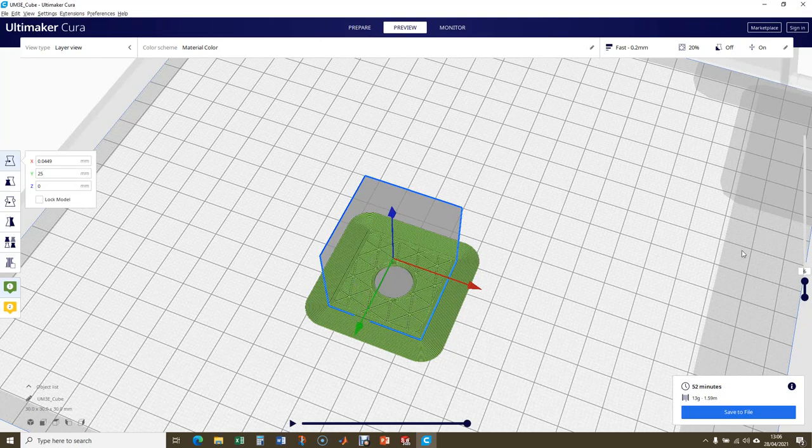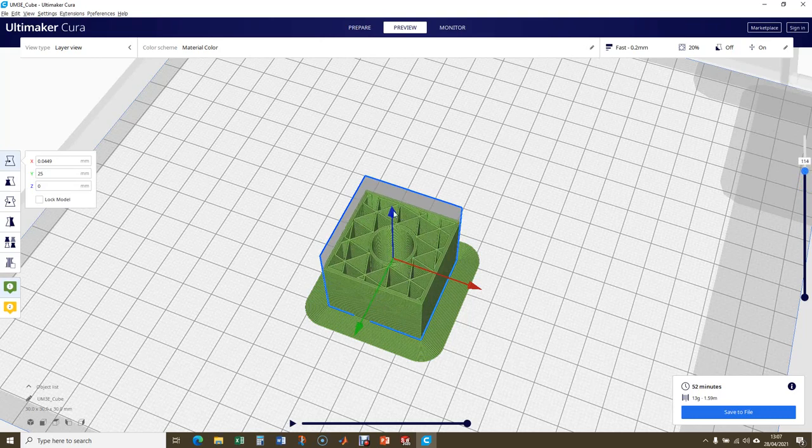In this case, I have triangles, and if we go up next, it builds up on those triangles, and that's to save material. If we had this all solid inside, for greater strength, we would use a lot more material. So for making parts on a 3D printer, you use percentage infill. So this is probably something like 20%, and in fact it says it there, so 20% infill.